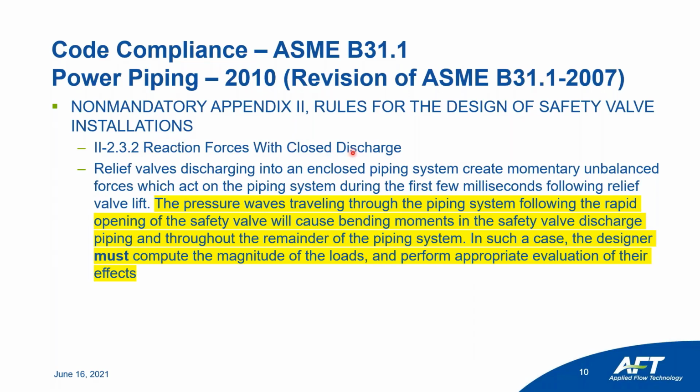The reason why I brought this up is because it doesn't give you guidance on how to calculate the dynamic forces. So what does the appendix say? Relief valve discharging into an enclosed piping system, and sometimes when it says an enclosed piping system, it refers to a header, creates momentary unbalanced forces which act on a piping system during the first few milliseconds following the valve lift.